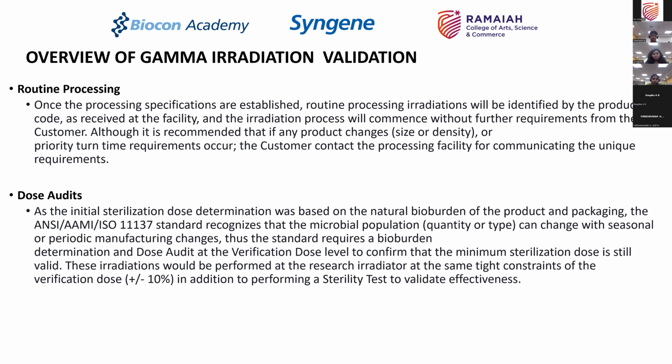Those audits, as the initial sterilization dose determination was based on the natural bioburden of the product packaging line. The 11137 standard recognizes that microbial population can change with seasonal or periodic manufacturing changes. Thus, the standard requires a bioburden determination and dose audit at a verification dose level to confirm the minimum sterilization dose is still valid. These irradiations would be performed at a research irradiator at the same test constraints of a verification dose, in addition to performing a sterility test to validate effectiveness. So, what does this mean?